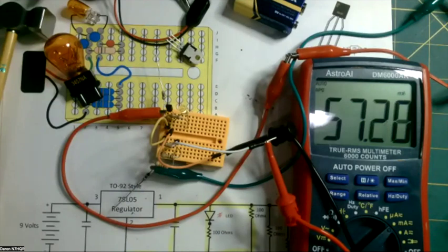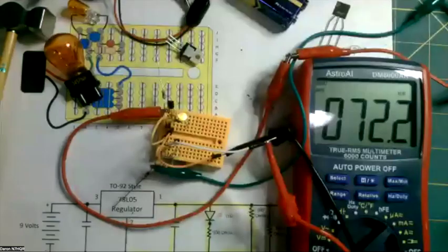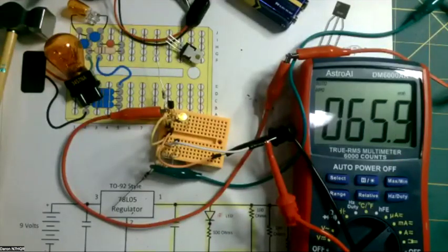So do we know what the actual voltage is? Before, when we did this, you were able to maintain 5 volts. Oh, we're 5 volts out of the regulator, yes. Okay, so if we take 5 volts from, where do you have your power supply set at? 13. So 5 from 13 is 8 volts at 60 milliamps. Is it hot? Yes, it is.